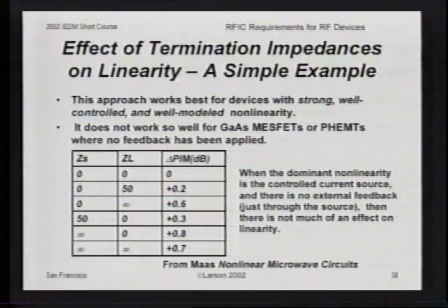And so this previous approach that I mentioned to you before works best for devices that have a strong, well-characterized nonlinearity, like a bipolar device. I mean, FETs, whether they're MOSFETs or gallium arsenide PHEMTs, are intrinsically highly linear to begin with, so the technique is not so effective, nor does it need to be so effective.